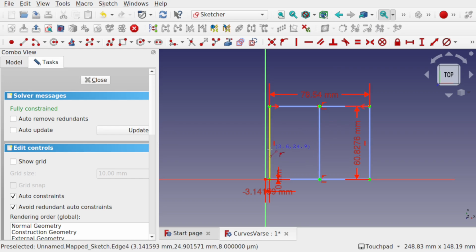So we can use a line in here. There is another way to do this, and that's to allow the arc's center points to rest upon these lines. So that line's in there. Let's make that construction geometry. This time I'm going to use a toolbar. And we've got that line in there.